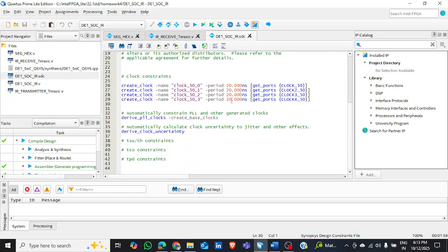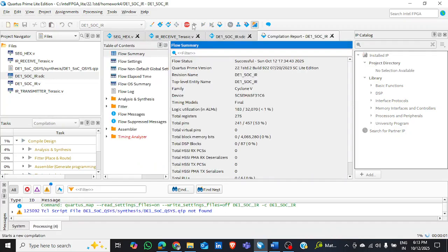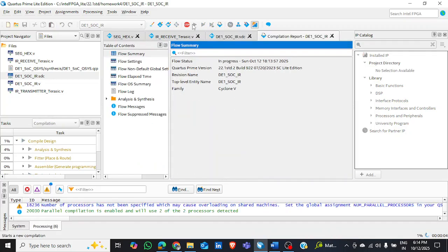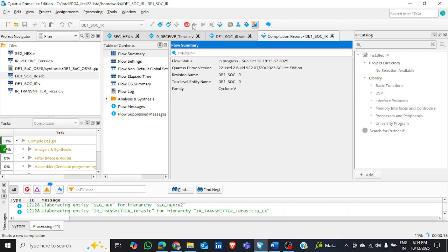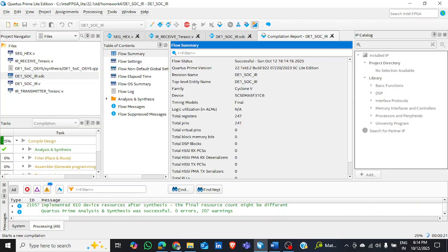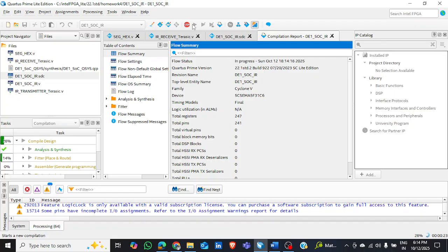For now, part 1 establishes a performance baseline. You just compile the design, so let us start compiling, and it's going to take some time. We compile the design and let the Quartus software automatically place and route the circuit in the most optimal way. You then measure its resource usage, looking at the Fitter, Analysis, resource usage or utilization reports, and then its maximum frequency using Timing Analyzer, and identify its single slowest signal path, which is the critical path.